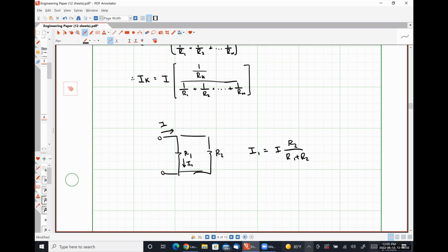The reason why that occurs is because there's physically a 120 degree phase separation between the coils in the generator. So if our stator is a circle, there is a physical 120 degree separation between the A phase coil, the B phase coil, and the C phase coil, which in turn causes our voltages to lag by exactly 120 degrees as we go from phase to phase.